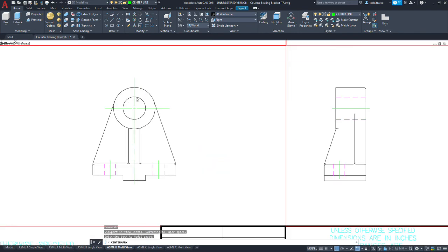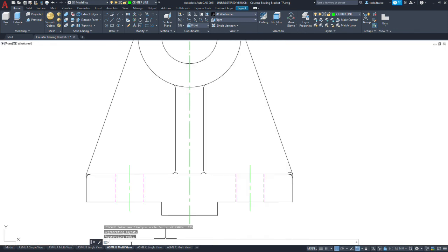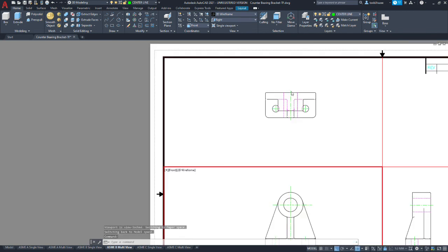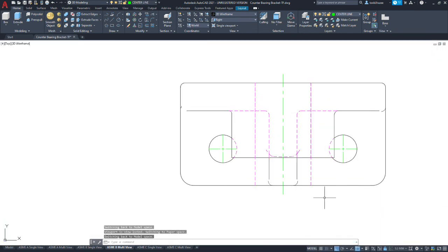Okay, so you're pretty well set up. It looks like we might need to change the line scaling a little bit. We had it set up for half a unit. So it's looking like to me that because we went with a 1/3 scale, we need to go back and change that. So I ended up having to do an LTS of 0.125 to have our spacing look correct. Now, I would encourage you to scrutinize that, and it should be matching the standard.